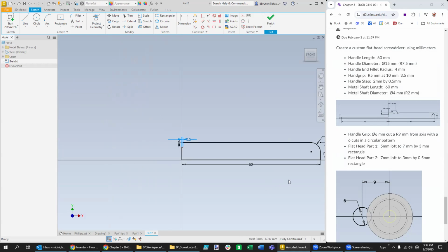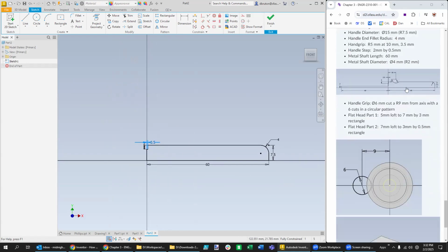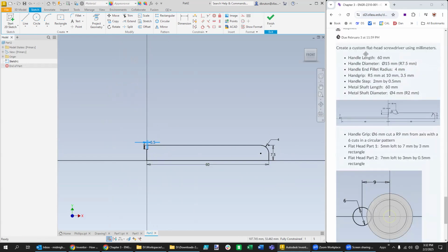All right, now it looks like there's also a handle or like a grip. So let's do the grip dimensions. So it says to place an arc, maybe a 3-point arc or maybe a center point arc. Let's try a center point arc. So we'll just kind of place it there to begin with, and then go over here and then hopefully lock back in right there.